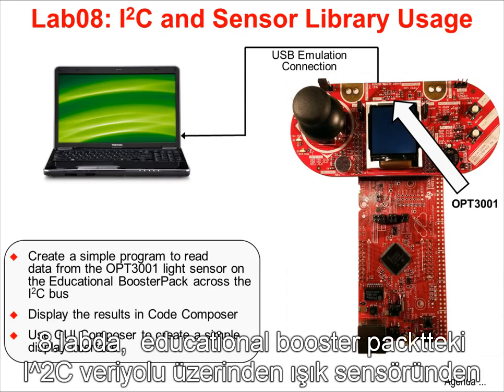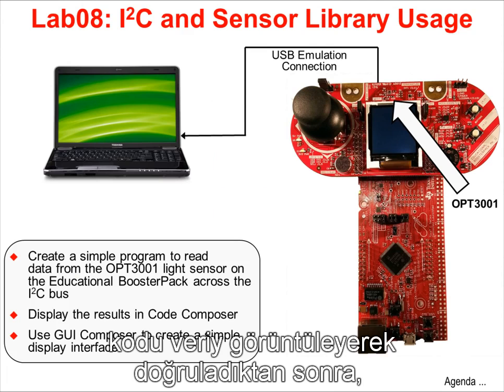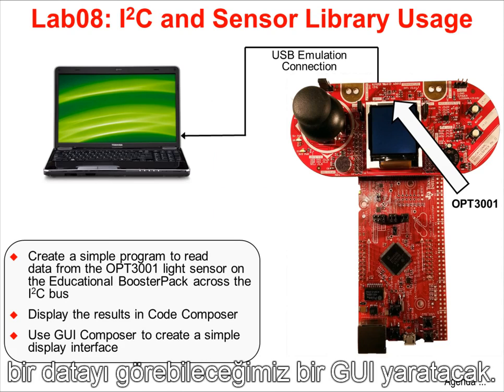In Lab 8, we'll create a simple program to read the data from the light sensor on the educational BoosterPack across the I2C bus. After we verify that the code is functional, by displaying the data in Code Composer, we'll create a GUI Composer display to show the data.